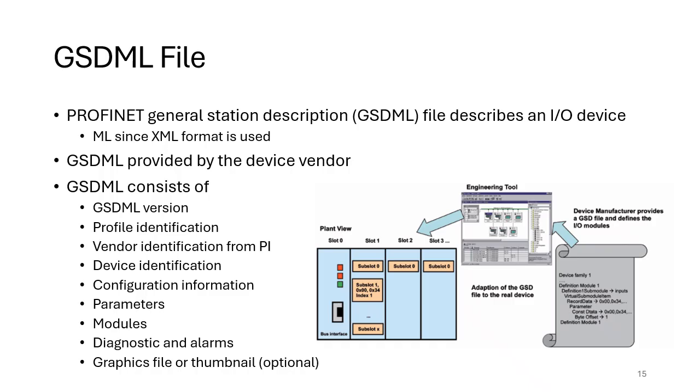It might be an uncompressed bitmap, and you might find your 5 megabyte GSDML file has 4.5 megabytes of that as the picture. So if you really wanted to, you could remove that picture to reduce the size of the file. And what vendors often do is compress those GSDML files so they take up less space on the device.